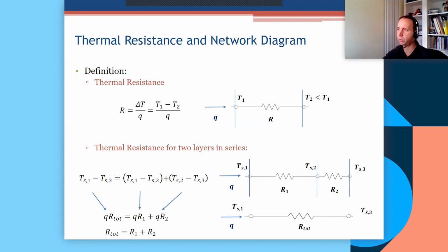If you want to relate the direction of heat flow, in a conduction problem, you would refer to the X, Y, and Z components of the Q vector. So Qx, Qy, Qz. So the temperature difference in this case, if heat flows from the left to the right, would be T1 minus T2, because T2 is smaller than T1, therefore T1 minus T2 gives you a positive delta